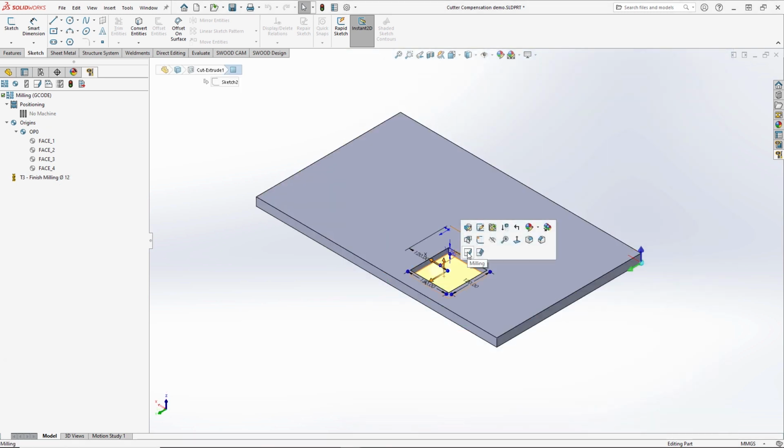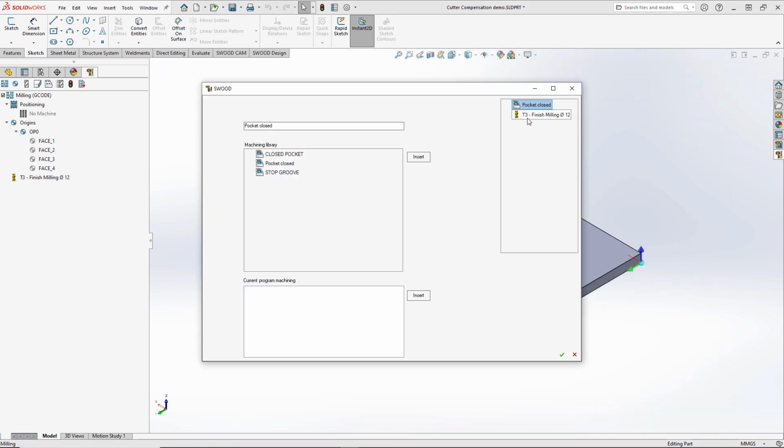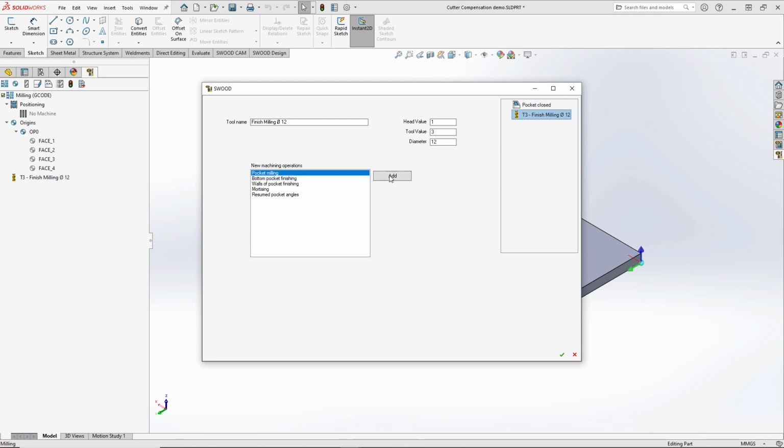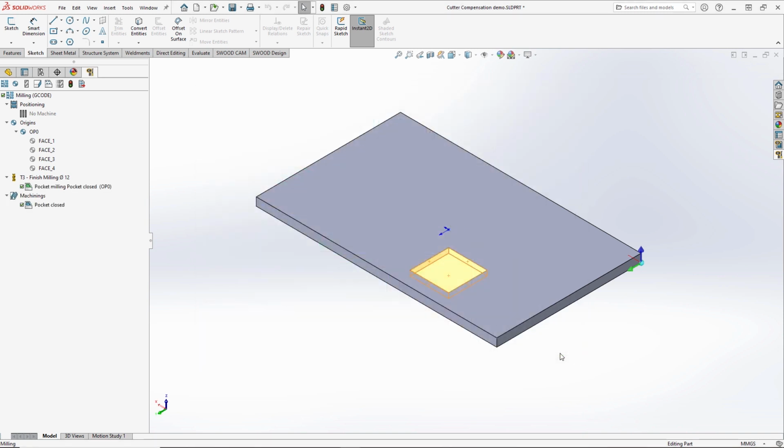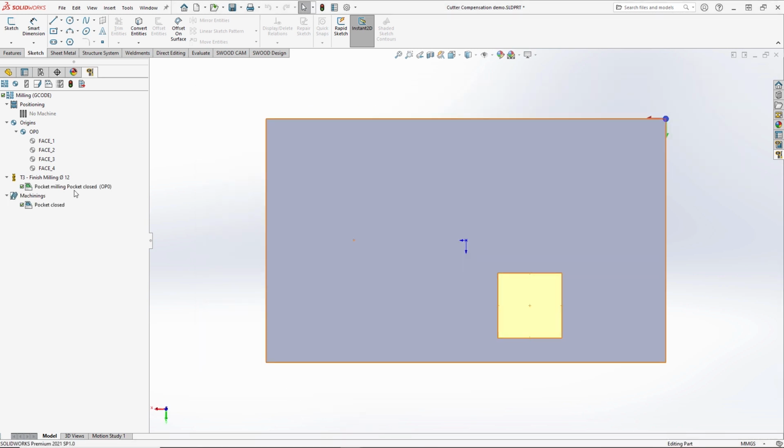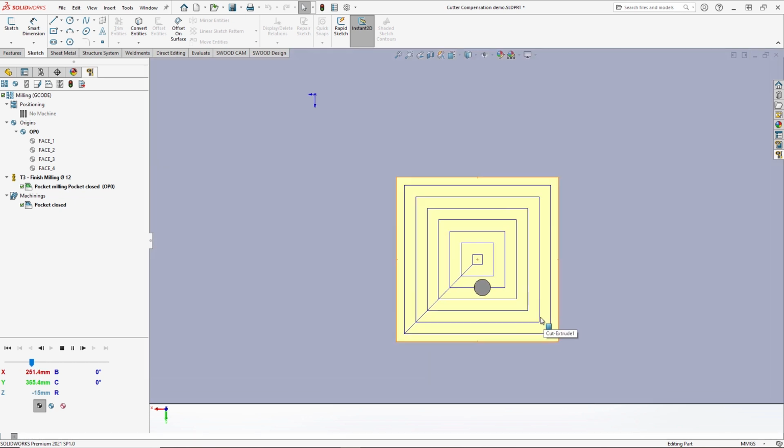It is common for users to combine a pocket and a wall pocket feature together, so it is represented as one machine operation, generating a toolpath cutting out the centre of the pocket as a roughing pass, then finishing the pocket using cutter compensation to ensure accuracy.